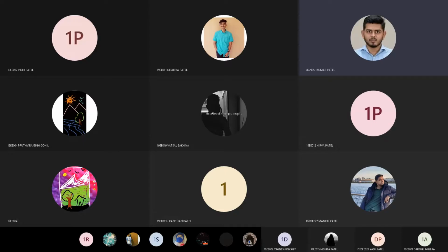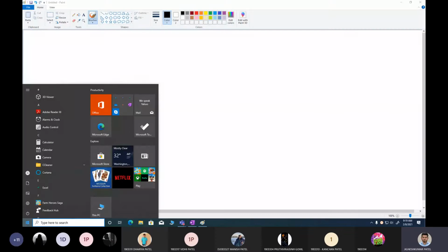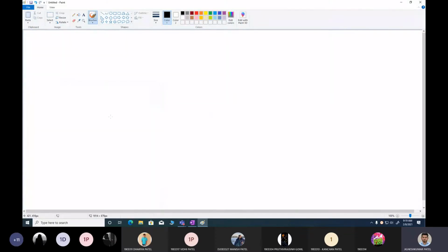Like, what are the other things we need to explain? So now we know a lot of things about 8085. By now we know what a control bus, a data bus, and an address bus are. We also know the different registers of the 8085. The registers are A, B, C, D, E, H, L. Other than that, there is one more register that we know, that is the program counter, PC.